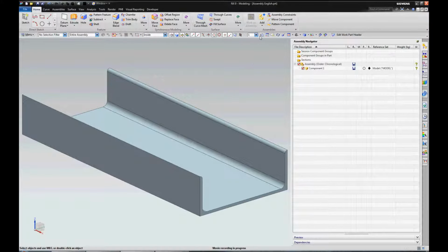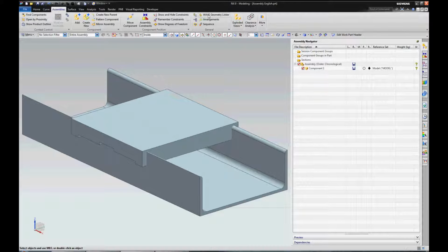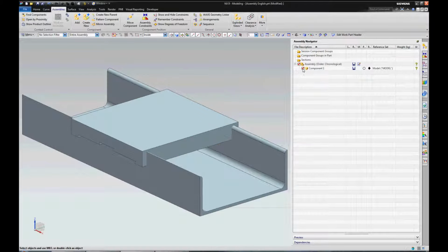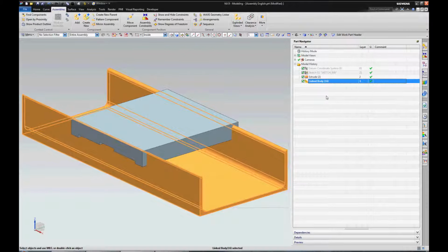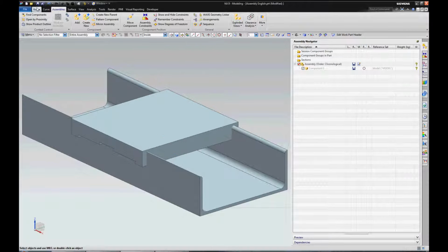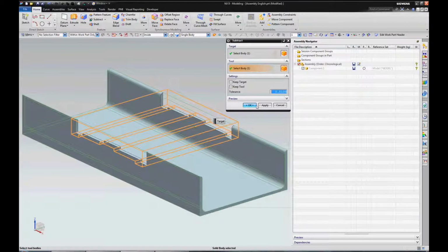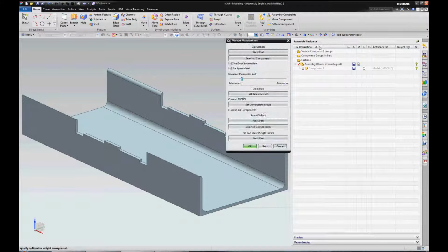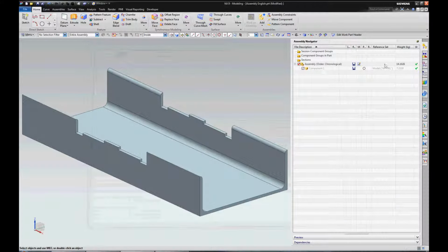Now a different technique, creation of a wave copy of a component body. The assembly is the same, the negative body the same, but we are creating a wave copy of a component body. We can see that in this case this isn't a promoted body, this is a copy. Let's do the same operation, subtraction. Be warned that the assembly weight in the case of this technique will be calculated wrong.